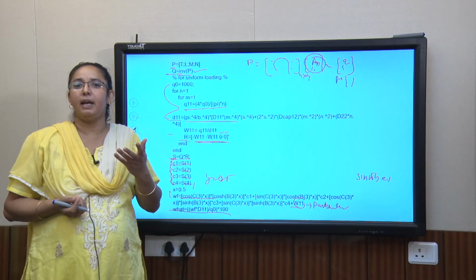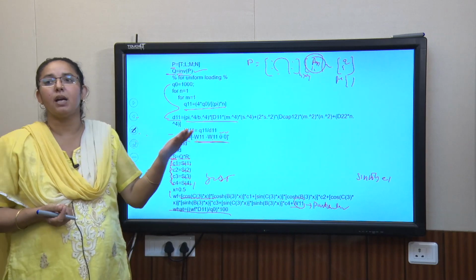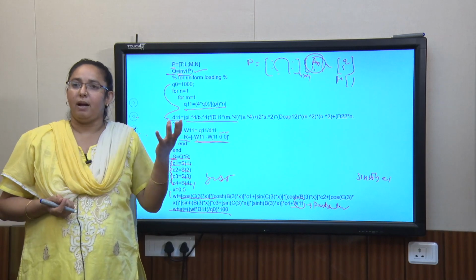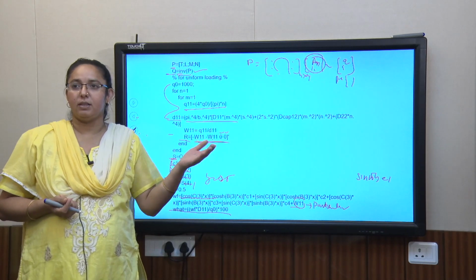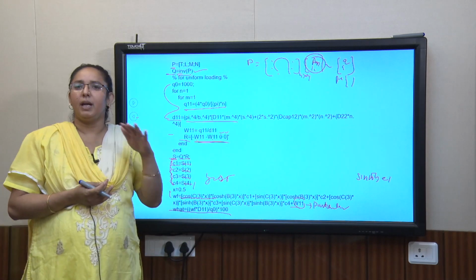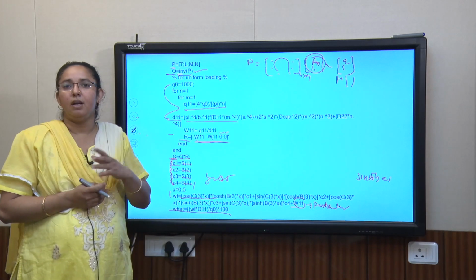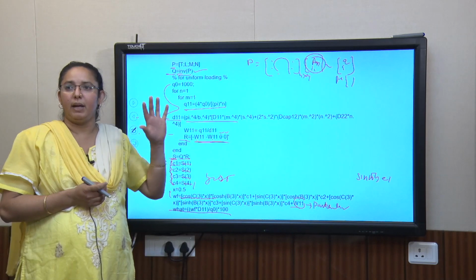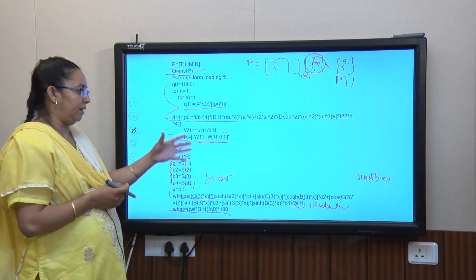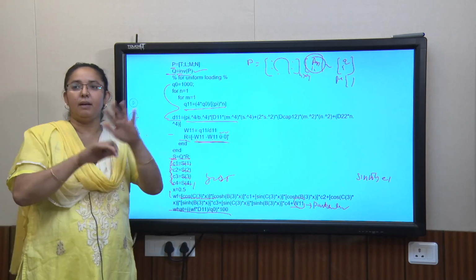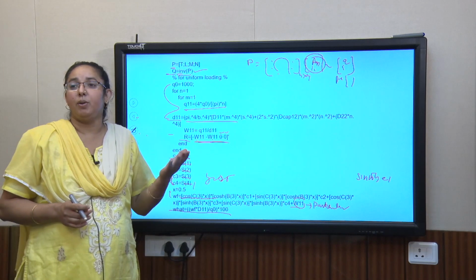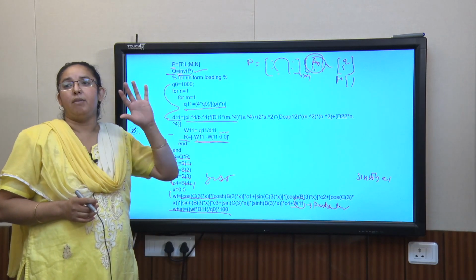These days as a second reference we choose commercial software. Sometimes we get the solutions from Abaqus or ANSYS. It depends upon the instructor's choice, in which he or she is comfortable. So we model the same plate and get the deflection plot, or the stresses and deflections, from our program and try to verify that. In this way we verify our codes.